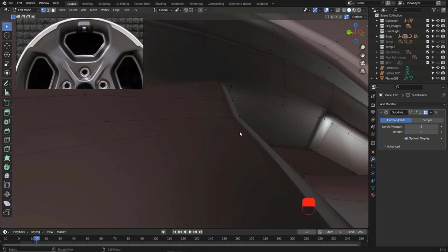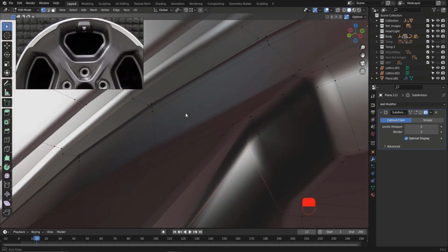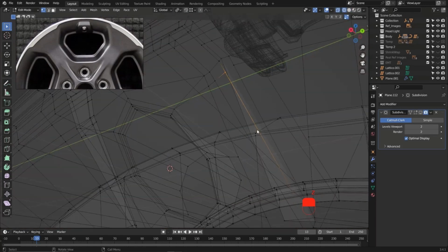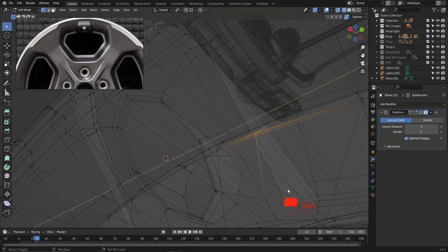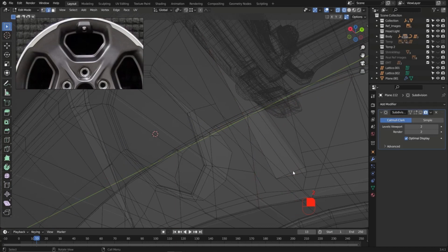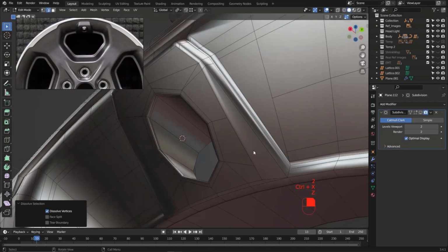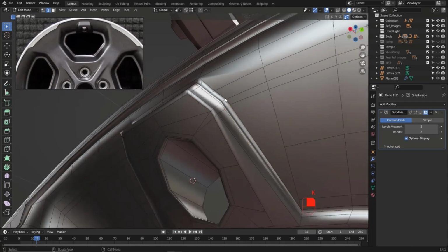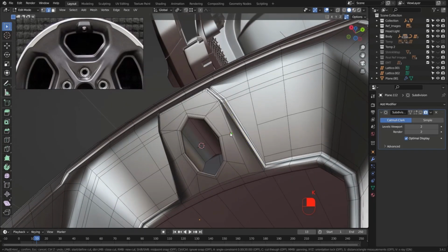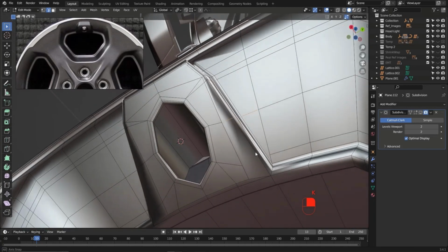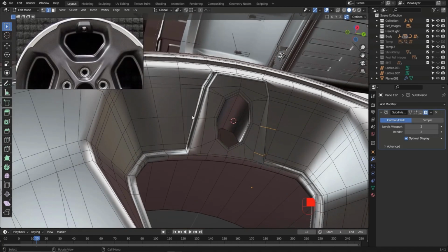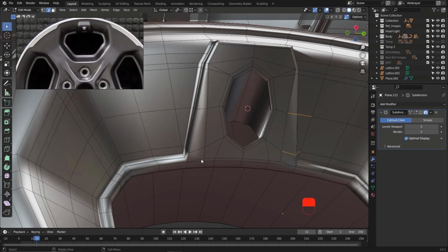All right, here, let's see what we have. Let's go to the wireframe. One of these edges, I think we forgot to dissolve. Yeah, now it's okay. Let's use the knife tool again and add this edge right here and create this edge here. And one edge should go like this, I guess. That will make this a little bit wider and that's what we want.